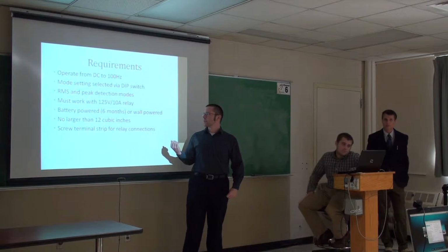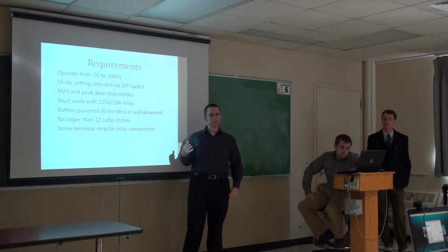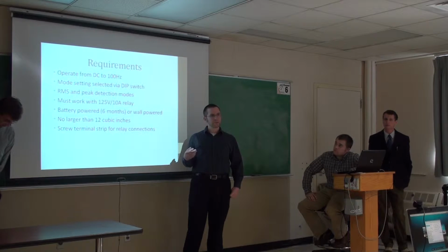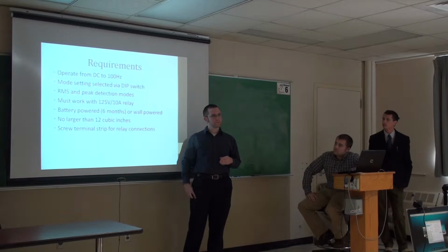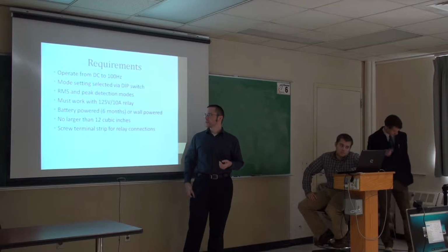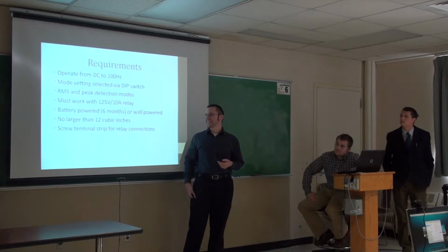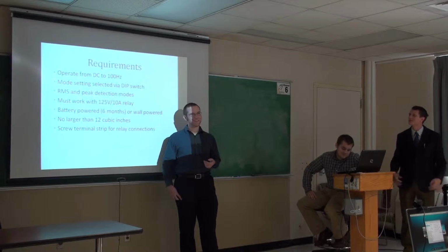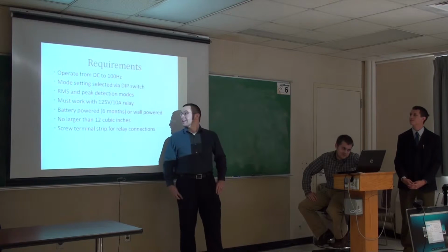We have to work with wall power and a high amperage. One of the uses for our device could be hooking it up to a washing machine. And that's quite a bit of current going through, about 1 kilowatt. So we need to be able to use a relay that can handle a lot of power.